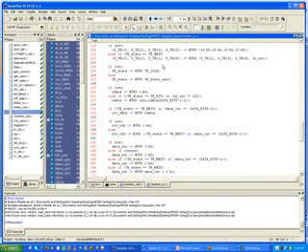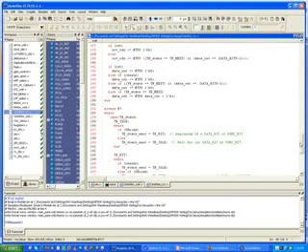Then let's go down to the actual state. Here's where I declare the flip-flops, basically, right here. Here I have a statement that says if reset, then I force my state to idle. Otherwise, the state is going to be whatever this variable called TB state next is. So that's the basic 2 flip-flops that get created, that will contain the state.